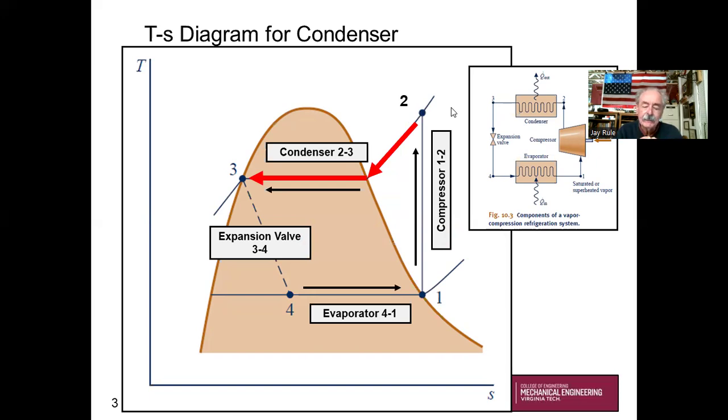However, if it's an adiabatic compressor with irreversibilities, it would be state 2a, or as your book would say, state 2. Let's imagine we've got state 2 pinned down in terms of pressure, which is usually given, and somehow we have found h2.